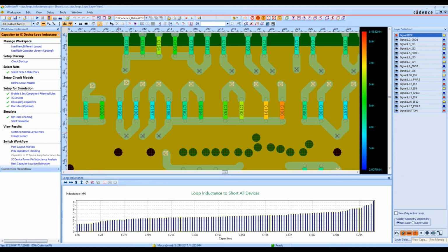Okay, and what is the highest frequency the AC tool can simulate? That's a good question. I don't know that there's necessarily a highest frequency. As far as the tools we're talking about here with optimized PI, your decoupling capacitors are only useful up to a certain frequency. At certain high frequencies, you move out of the domain of usefulness for decoupling capacitors on your board, and you move into needing on-die or on-package capacitances, the ones that are closer to the source.